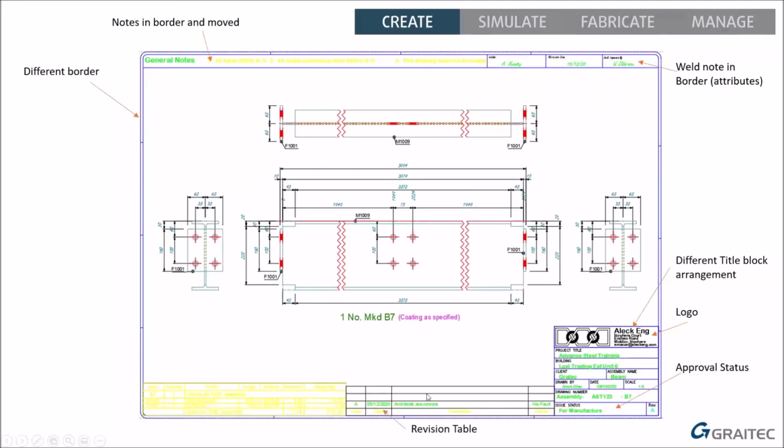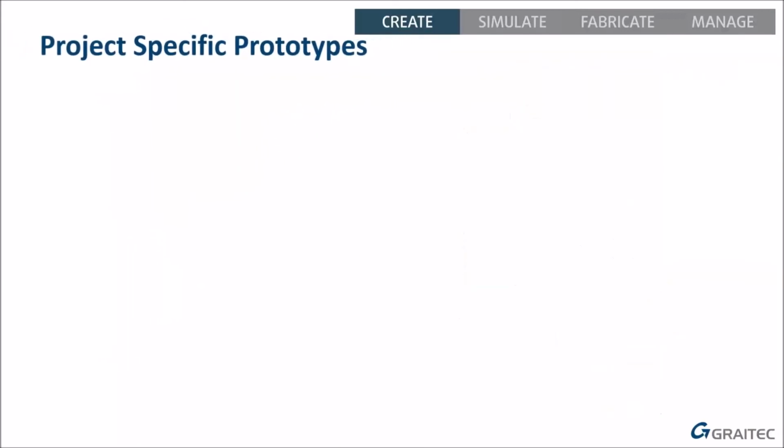I've moved the revision table. I've changed it to 3 lines. I've only got one BOM. I took away the lot list and I've resized it to fit the available space. Also, the dimension styles, you'll see I've changed the arrowheads and I've changed them to a nice font, a different font. Looks more hand-drawn. So you can make quite a different look.